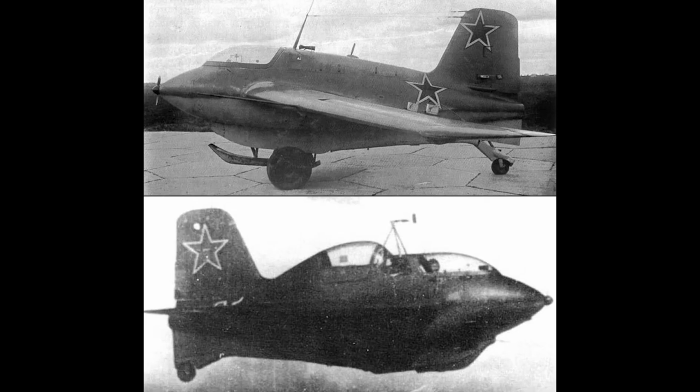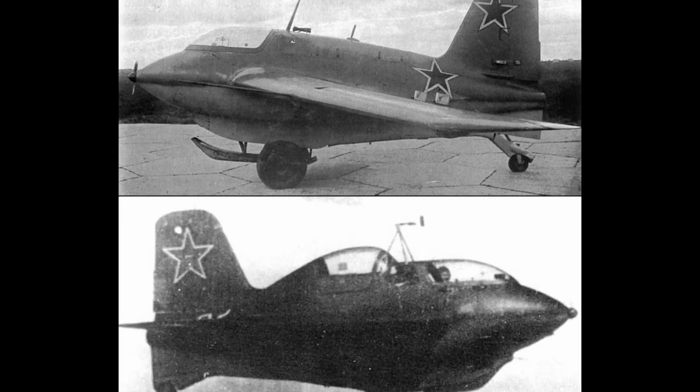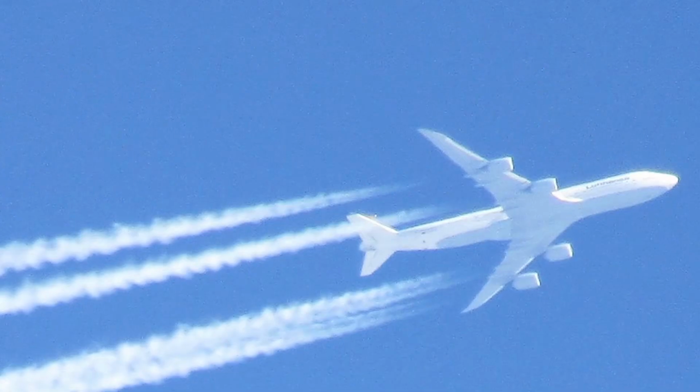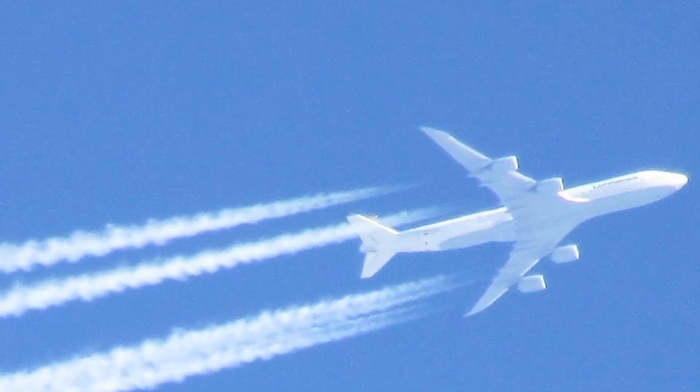In other words, the plane could go faster without the shock wave appearing. As it's always said, necessity is the mother of invention, because it wasn't until they needed it that they actually discovered it. And this is the main reason why it's still used today. For example, a Boeing 747, which has a high wing sweep angle, can fly at pretty high Mach numbers. If it weren't for this, it would be completely impossible. Shockwaves would appear much earlier.